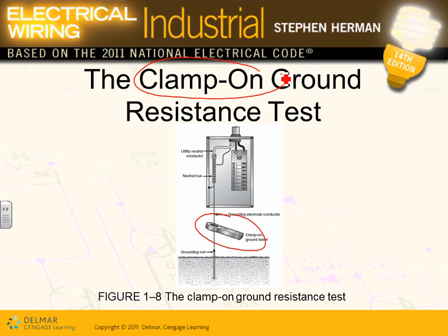Instead of measuring a current, that clamp on meter, guys, has 2 coils in it. One coil, believe it or not, shoots current. The transformer shoots current right into the rod. So you will shoot from here current right into the rod, and then another transformer or coil can measure the current that's coming back. So by shooting current and measuring the current that's coming back, they will determine the resistance of the grounding system.